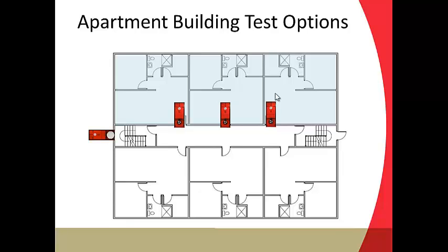We could set one up in the hallway and bring the hallway to pressure because that's an adjacent space too. And then we would also set up a fan above and below. So in this case, we'd need 1, 2, 3, 4, one above and below would be 5, 6 fans to keep all adjacent spaces up to pressure.